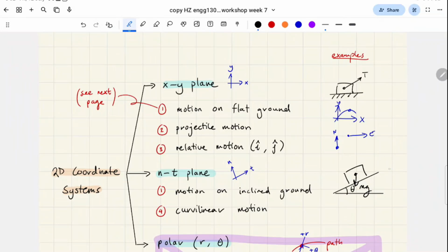Sometimes you have friction, sometimes you have the direction that's being pulled, or it could even be inclined like that. And the normal force is always perpendicular to the plane. So usually you go mg, then n, then friction. It helps with the unknowns, which are generally n and f, to break things up by taking the sum of the forces with respect to the normal and tangential directions.